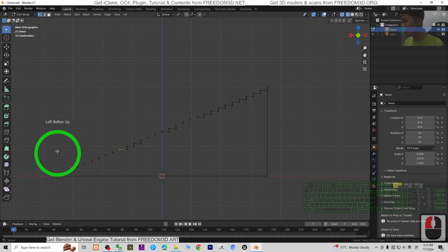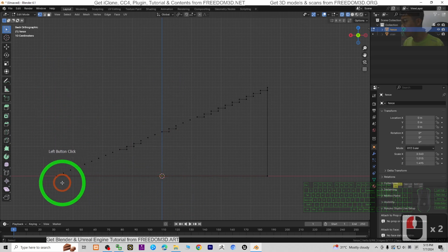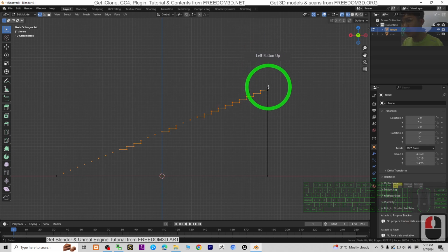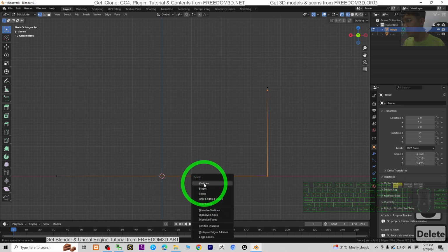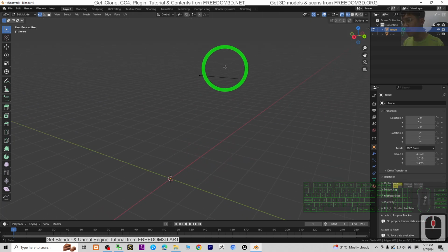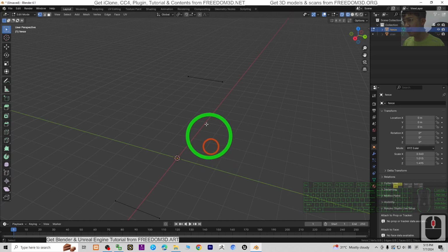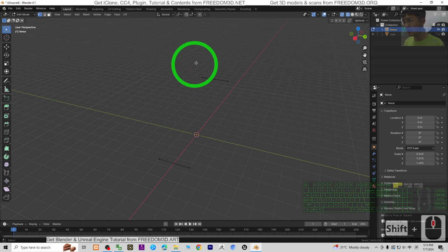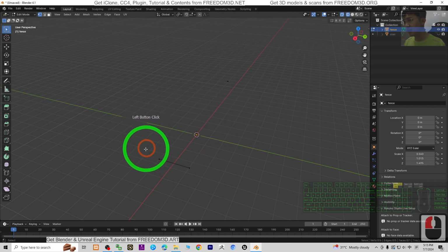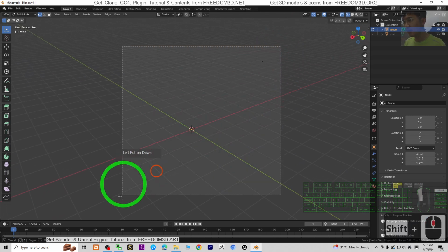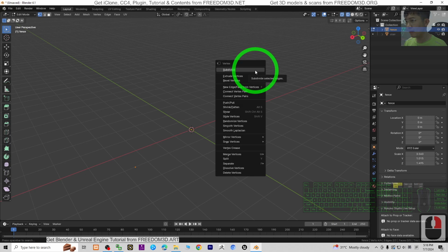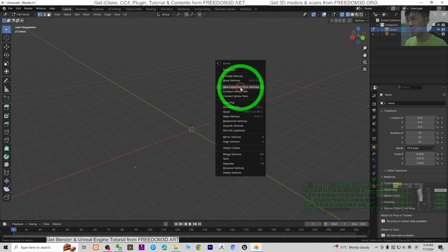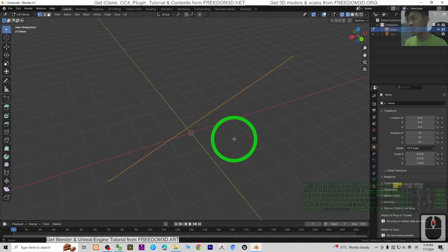Just switch back to select box. We just want the two ends of the vertex. The rest you can just delete. Right. Now you just have left these 1, 2, 3, 4 points. You can delete this one and here delete. So select two of them. You can see two vertices, right click, then new edge face from vertices, then subdivide it.